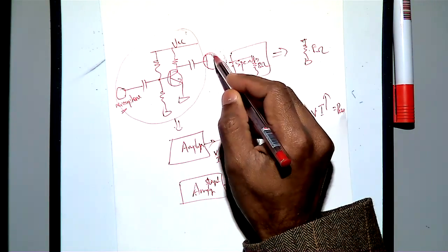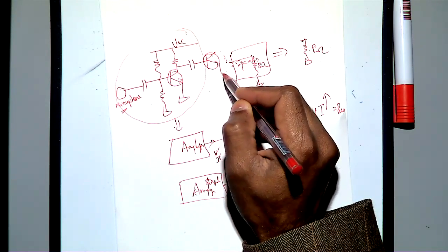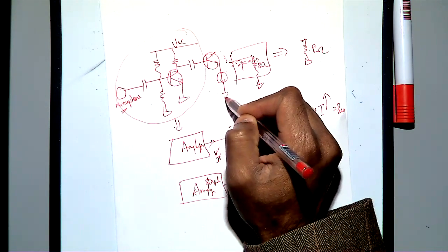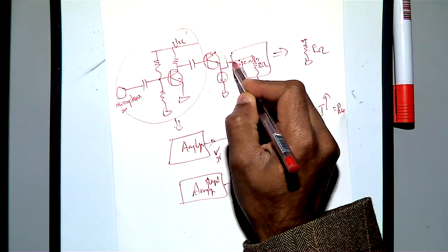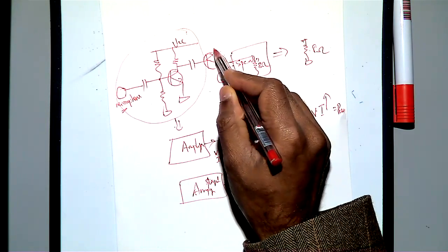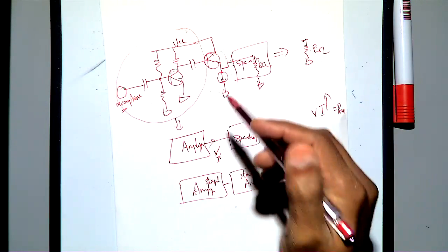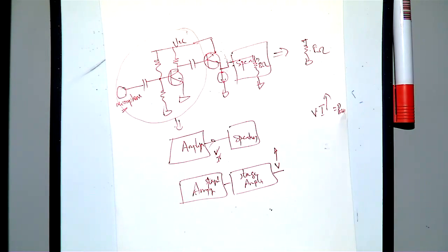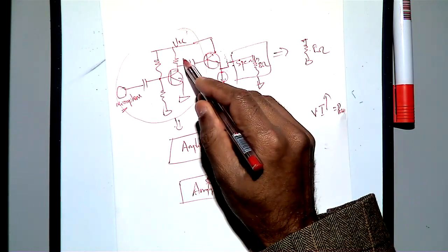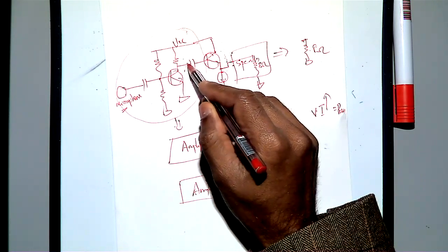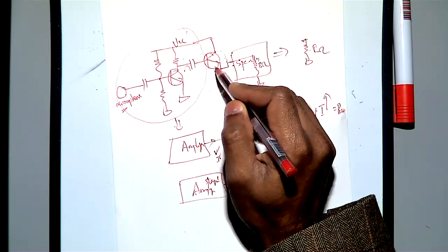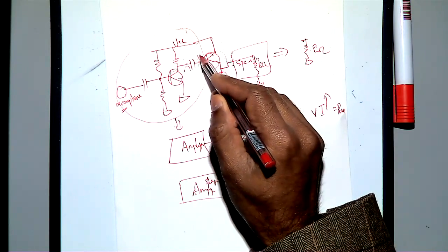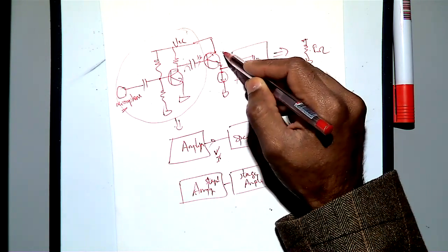So if you connect an emitter follower, maybe you can design a current source, or you can connect a very high resistance here. And this will solve some of the problems. I wouldn't say all of the problems. If you do this, this is your voltage. The voltage for the signal will pass through. And the current is IB here, and then your emitter current, IE.